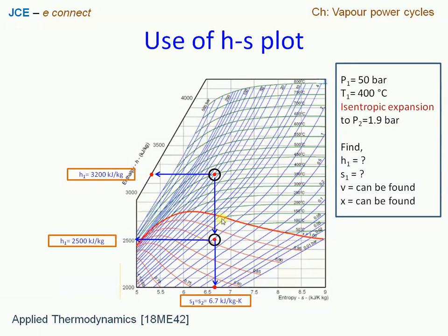Therefore we have a system here undergoing an expansion process where heat is rejected, or is absorbed. Heat is rejected in fact. So therefore we have H1 minus H2, the difference in H1 minus H2. This is H2. Please make a note of this. This can be interpreted as the amount of change in enthalpy that has gone into producing the turbine work.